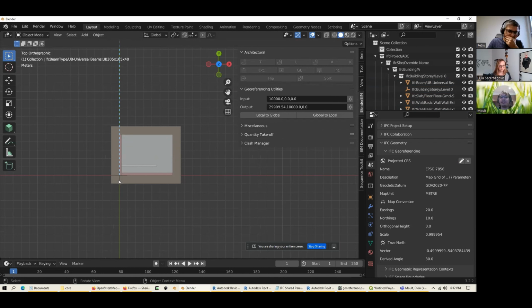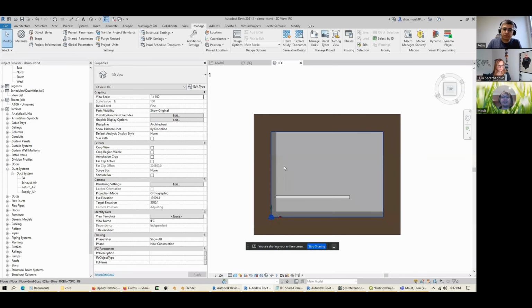You know, if you're doing a train station, for example, and it's a few hundred meters from end to end with buffer on either end, don't choose your false origin to be at one far end of the project, because by the time that you move to the other end, if anybody on Revit is using the eastings and northing tools, they're going to get a wrong number.